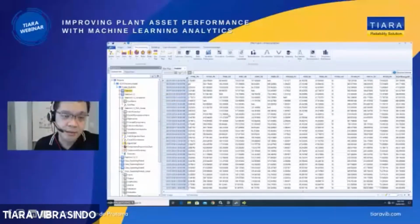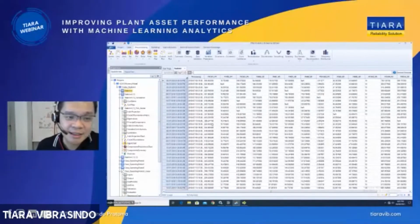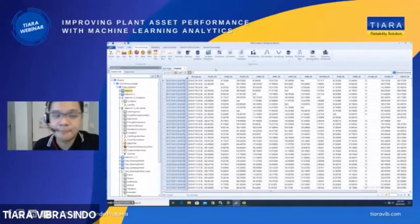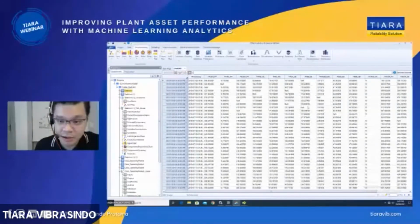Now, the first thing when you want to do modeling, you may remember somebody saying to you: if you have garbage data, you will create a garbage model. So the first thing we need to do when we come to modeling is data pre-processing. In fact, when we do data modeling, data pre-processing will take up 60% of the time. You have 2 years of data, you need to clean it, because the truth is our sensors are not perfect. Our sensors have a lot of noise, sometimes spikes, sometimes drift, sometimes they lose connection. That results in something you can see immediately, which is no data. These are the NaN.